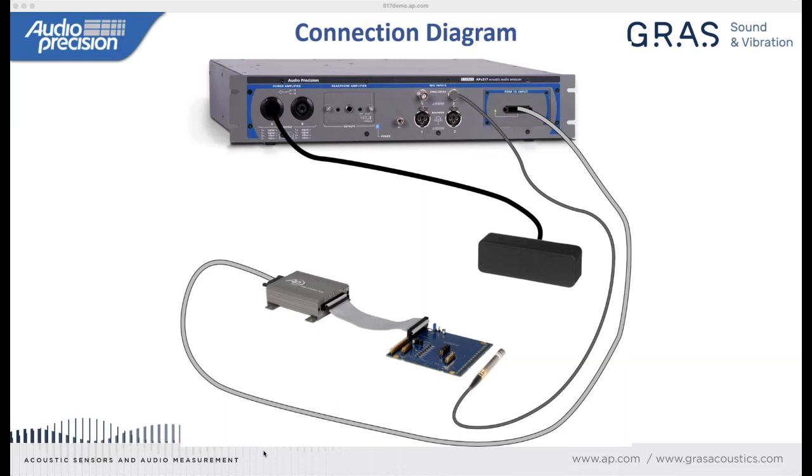And then I've got another question about 1/8-inch microphones. 1/8-inch measurement microphones do exist. They're a little bit esoteric, relatively rare and expensive, but they do exist. And exactly in the situation where you need to measure to high frequencies, that's really where they become quite useful.